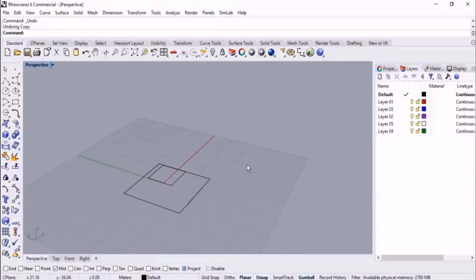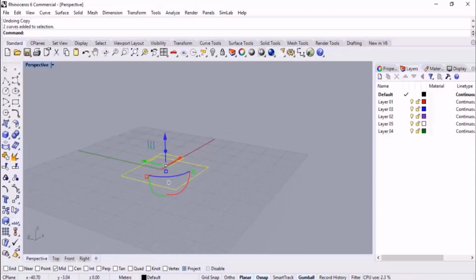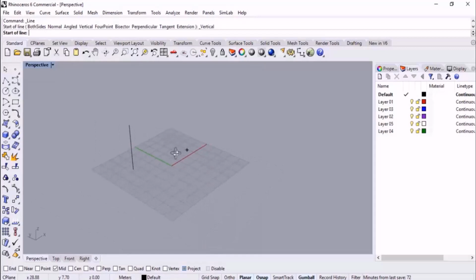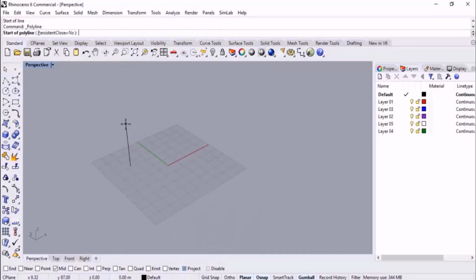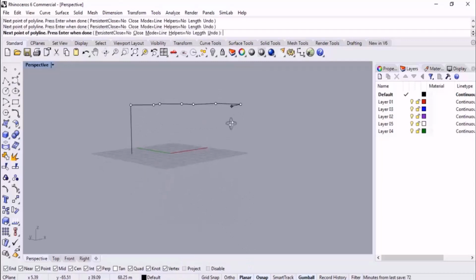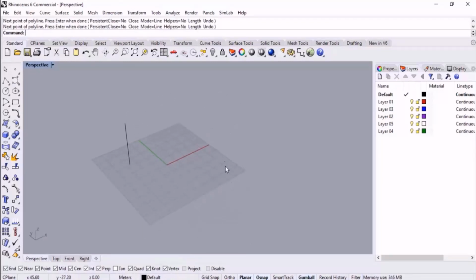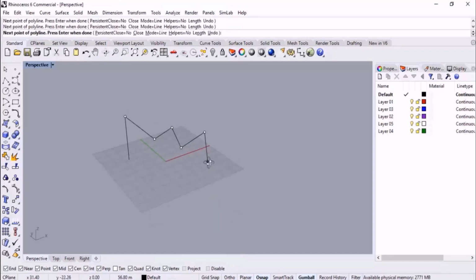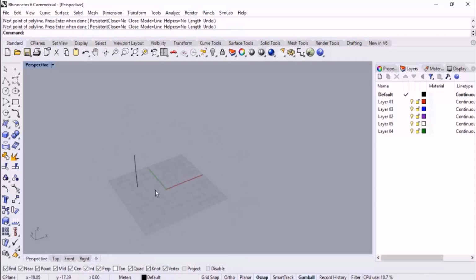And the final point: some of the auxiliary commands constrain the curves or the sketching from changes in planes. For instance, I sketch a vertical line perpendicular to the work plane. Then here, if I keep the endpoint to continue the line, with project disabled and planar enabled, I sketch the lines. We have them at the same level or height. But if I disable planar, then we will have differences in the height of the points. Check this out, they are placed on the origin.